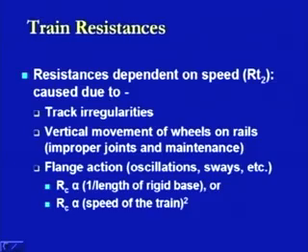If we talk about the joint of the rail, at that point both the rails should be at the same level. If they are not at the same level, and the wheel moves from one rail to another rail which is at a higher level, there is going to be a vertical movement at that point, and this is termed as jerk. This is the proper technical word used for this movement.